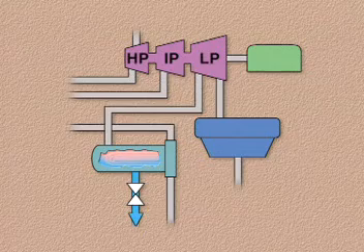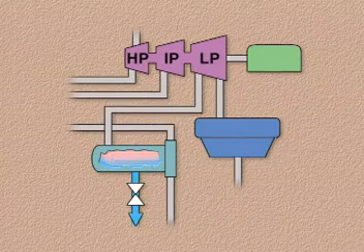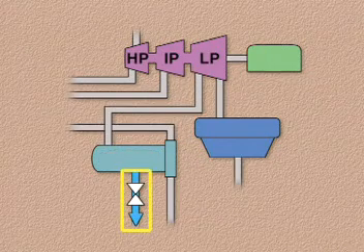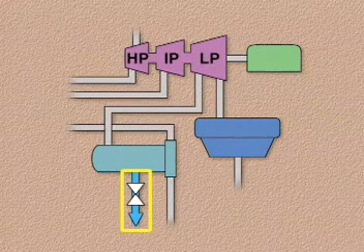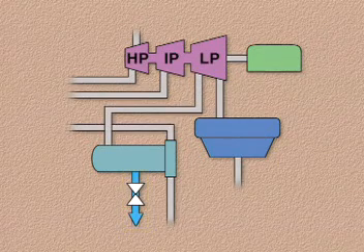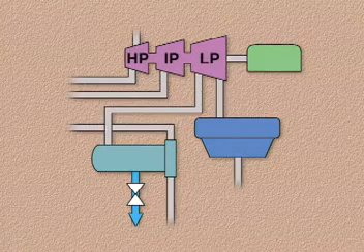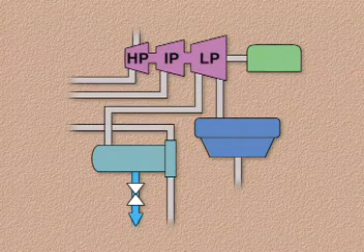Likewise, high level is generally not a problem in low-pressure systems because water in the drains for the feed water heaters usually flows directly into the condenser. The drains are large enough to keep the water level from getting too high and to keep water from entering the turbine.